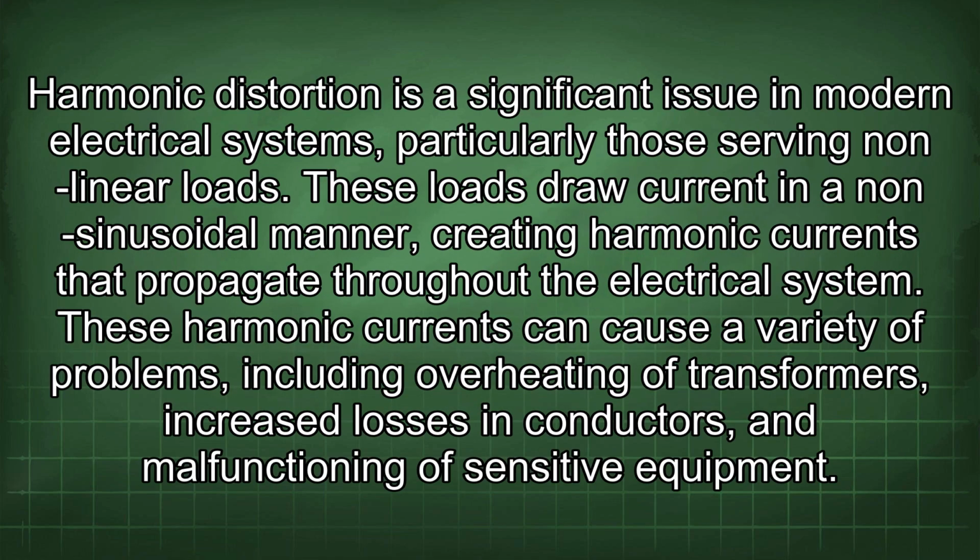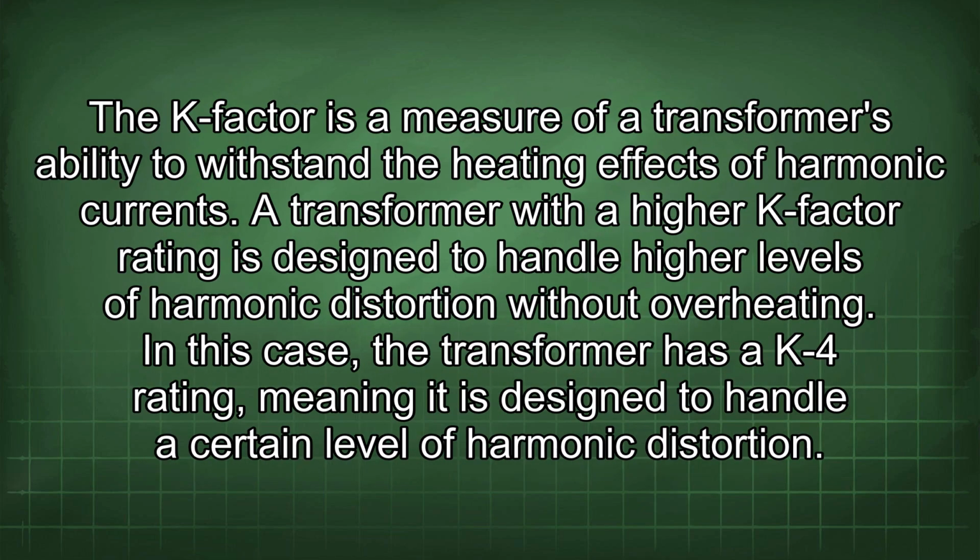Harmonic distortion is a significant issue in modern electrical systems, particularly those serving nonlinear loads. These loads draw current in a non-sinusoidal manner, creating harmonic currents that propagate throughout the electrical system. These harmonic currents can cause a variety of problems, including overheating of transformers, increased losses in conductors, and malfunctioning of sensitive equipment. The K-factor is a measure of a transformer's ability to withstand the heating effects of harmonic current.